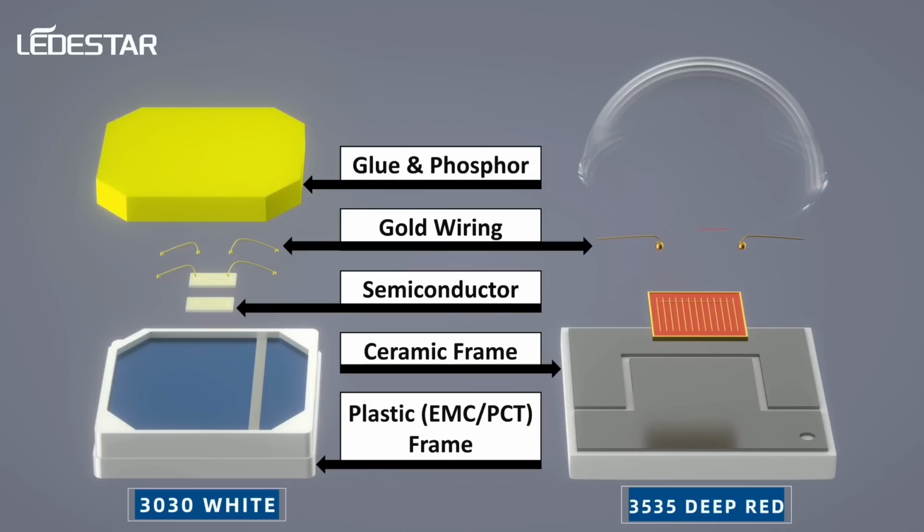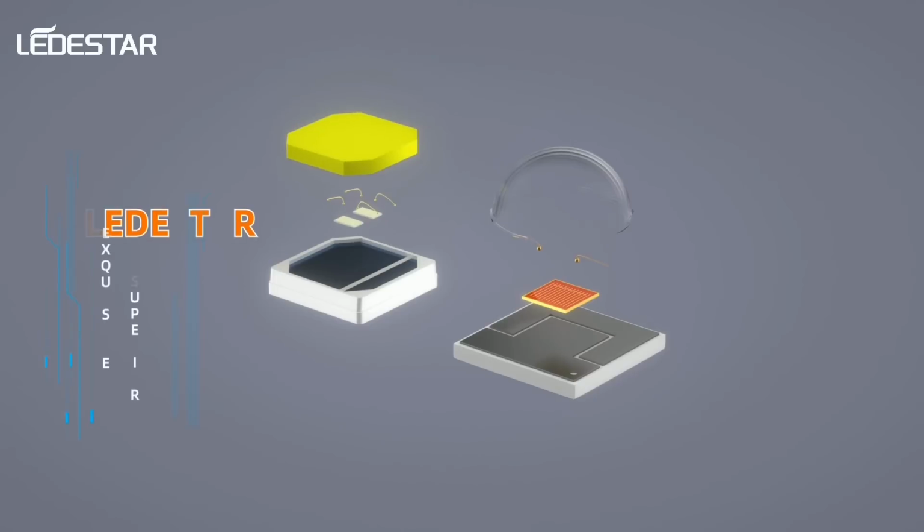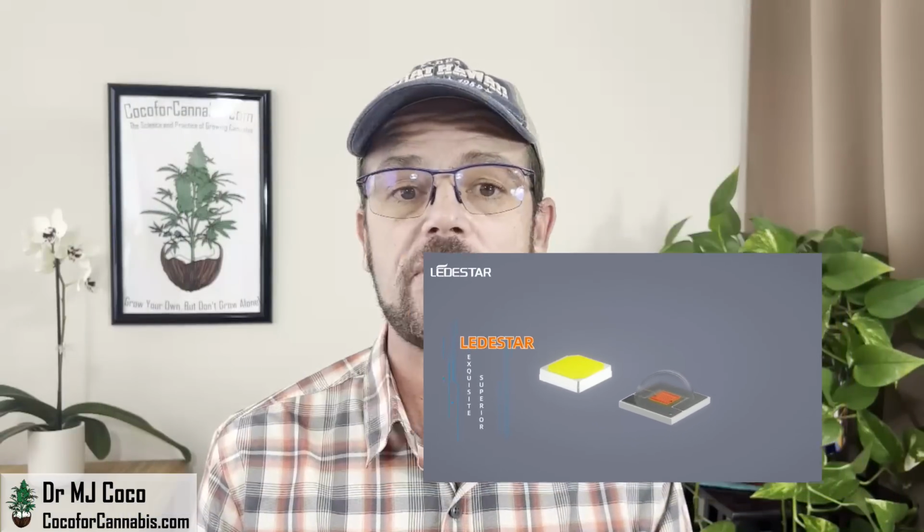Again, they use gold wiring, and there's always a semiconductor. In this case, it's a 660 nanometer semiconductor. Single wavelength diodes may use glue as a cover, but since they do not have to filter the light, they can also use a clear lens, like the Lettistar 660 nanometer diode here. Okay, so that's what a horticultural LED is and what they're made of.